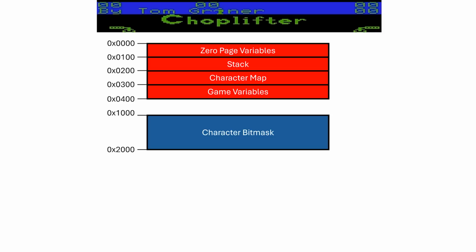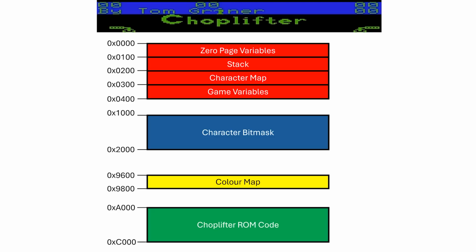This is actually the primary reason why I think the VIC-20 came with 5K of RAM. It's really the minimum required to do bitmap graphics for a game running off a cartridge located at 8000 hex. I suspect this was the money configuration they had in mind when designing the system.